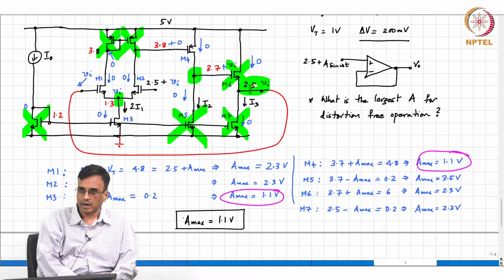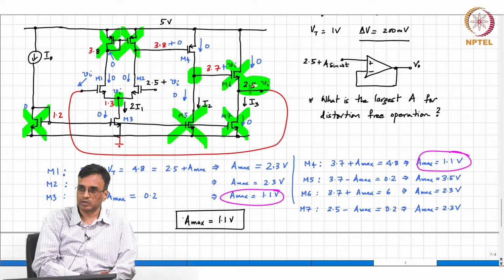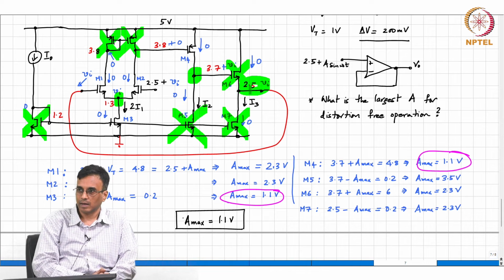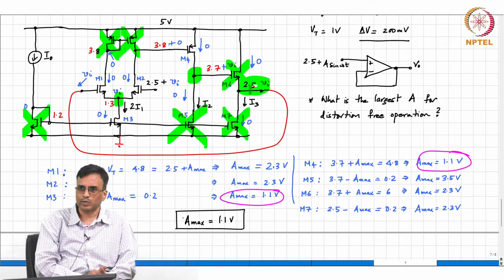The feedback loop is closed through the base station, Airtel, maybe with Zoom it's going to Europe and coming back, and the loop is closed that way, but there's a lot of delay in the whole process. So whenever you have a high gain negative feedback loop, you have to always worry about stability. Nothing comes for free.